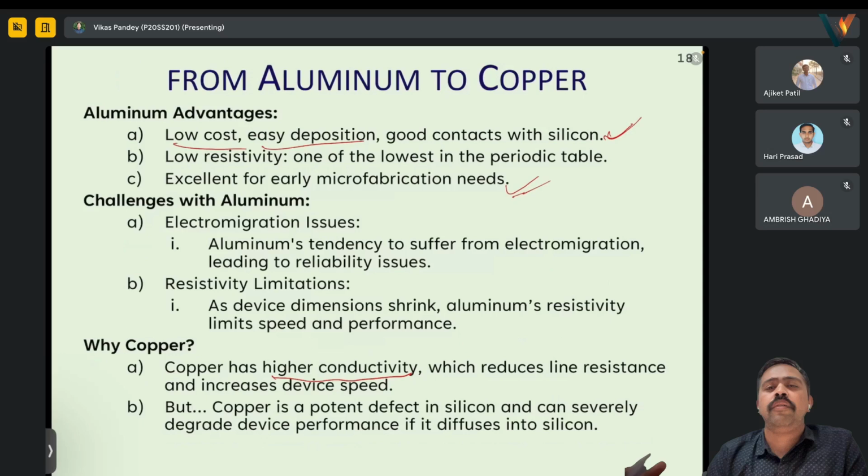We see the sticking coefficient, but again we have to take care that along with the sticking, we have to do these processes at lower temperature. CVD is a process that is at high temperature. And if you are talking about ion implantation, that is next to the surface. Deposition using implantation is a big issue. Okay, sticking coefficient also has an impact on the deposition.